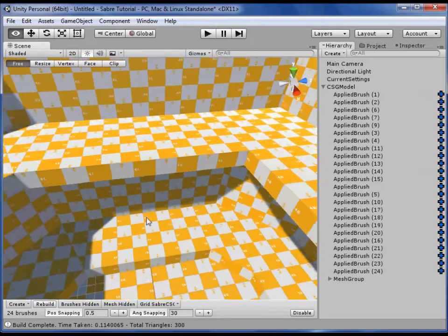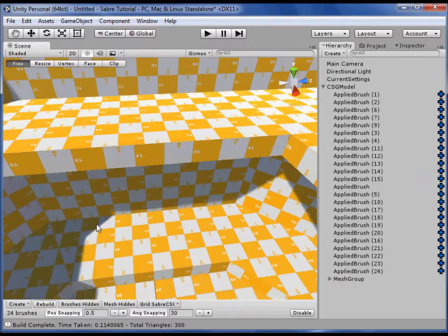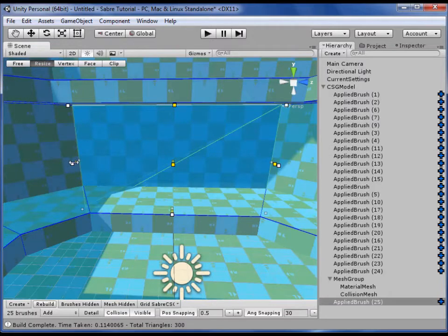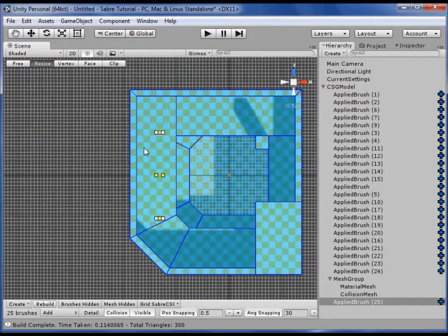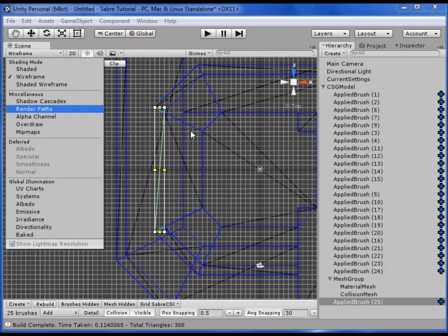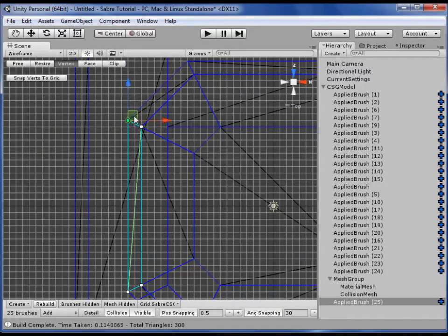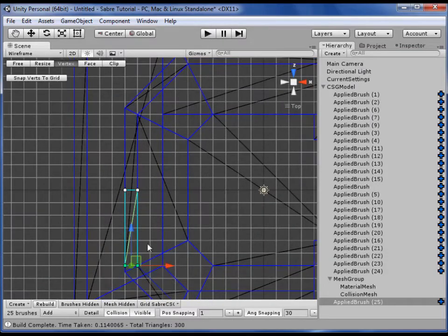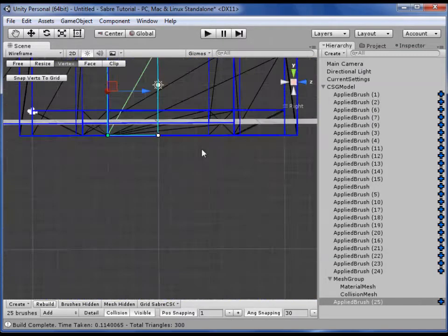So I think the way to do that is just to start by creating a doorway in one of these lower walls. So I'm going to first just select the wall and duplicate it. And before I start resizing it, let me switch to a top-down view, make that wireframe, and just adjust these. That way I can increase the scaling. Everything stays nice and happy.